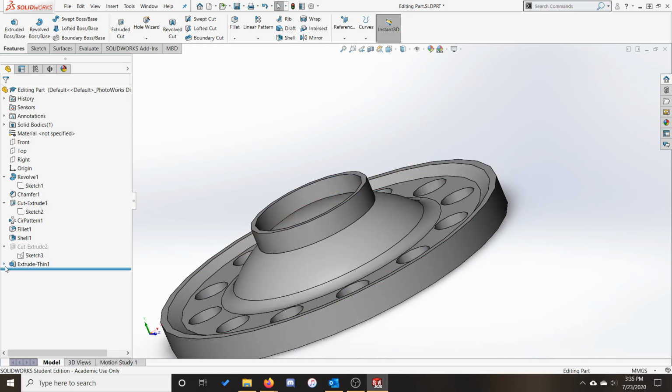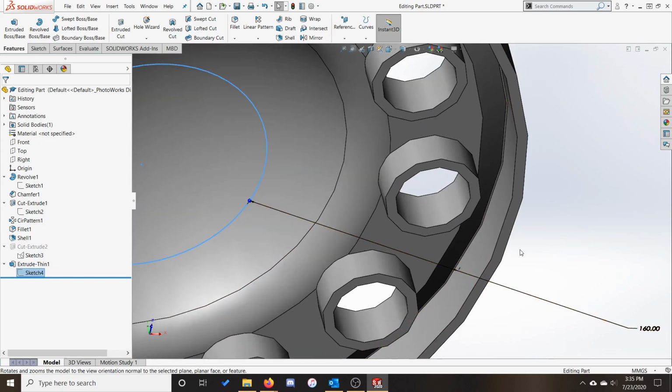For example, because of the way that this tube feature was defined, with the dimension going to the inner surface of our shell, we can't move the tube to occur before the shell. We could change the way that the dimension was defined, but this could potentially violate design intent.